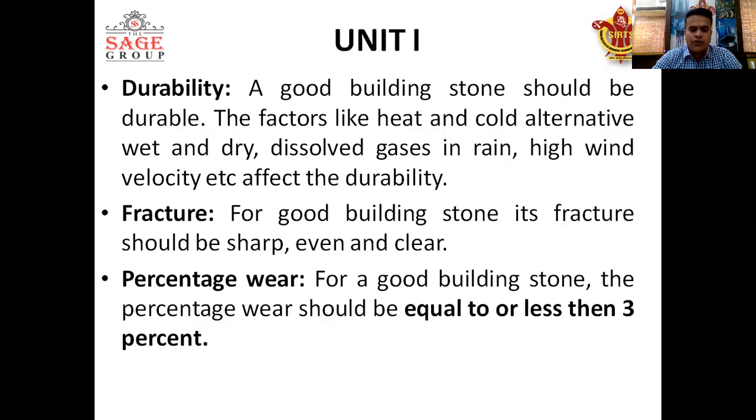The percentage of wear of a good building stone should be equal to or less than 3%. Now I will tell you about the wear. Wear is a phenomenon in which stones rub against each other, and due to the rubbing action, the stones should not convert into powdery form. If a stone converts into powdery form, it is not fit for use in construction work. So it should have a wear percentage of less than 3%.